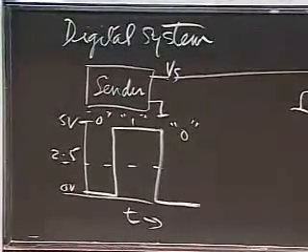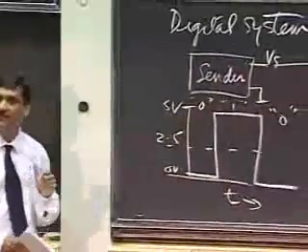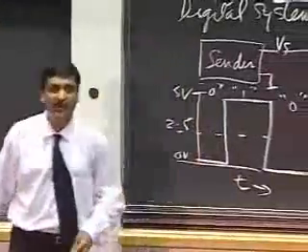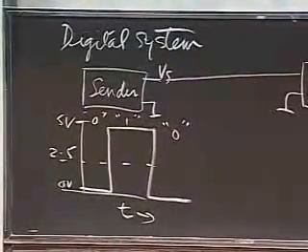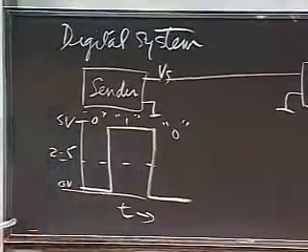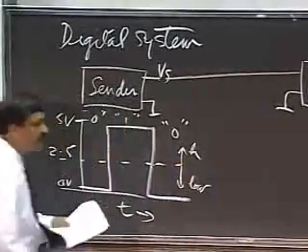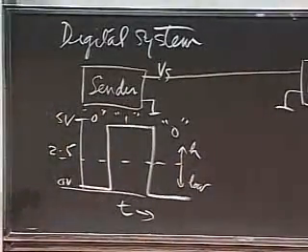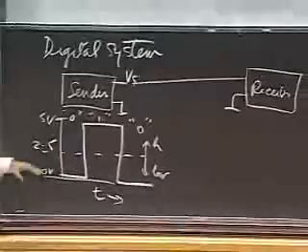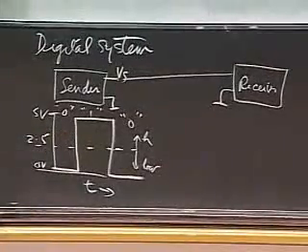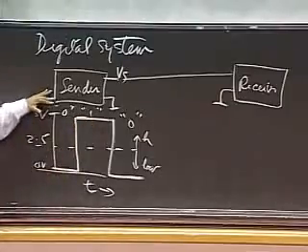It's a symbol. That's why I have put 0 in quotes there. We'll go into this in much more detail later, but for now, suffice it to say that I'm sending a set of signals here, 0, 1, 0. This simplistic scheme will not work in many situations, but go along with this for a few seconds. So I send the signal sequence 0, 1, 0, and notice that there is a high and a low. The agreement the sender and the receiver have is that if you see a value higher than 2.5 volts, that's a high. If you see a value below 2.5 volts in the wire, that's a low. I'm going to send a 0 volt or a 5 volts from here.